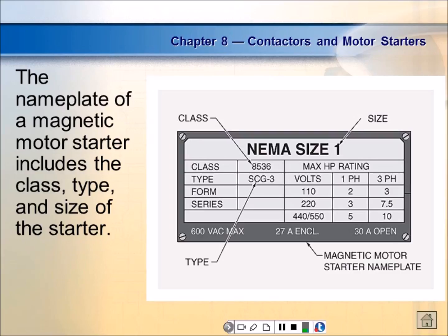So that means if I run it for low current, I can use smaller conductors to get it out to the motor, and my relay contact can be smaller. So instead of using a size 2, I can use a size 1, right? Are we okay?